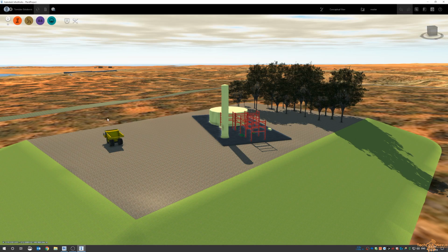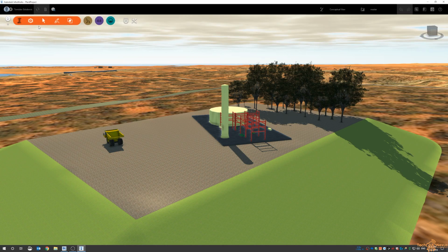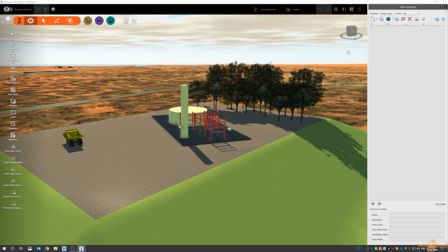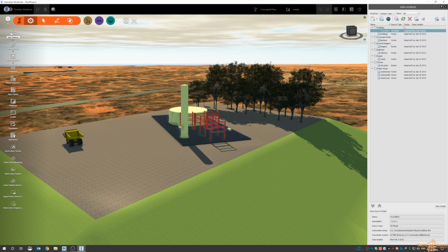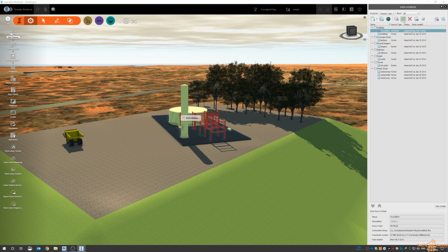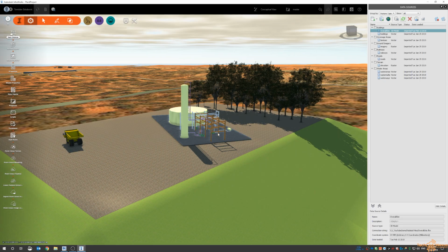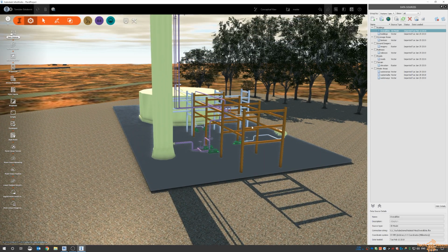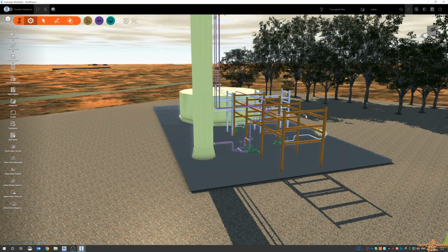What happens now is we jump into InfraWorks. And this is just quite an easy process. We look for the FBX file, we refresh the data source, and then that's just basically InfraWorks' way of reloading an XREF coming from our project.